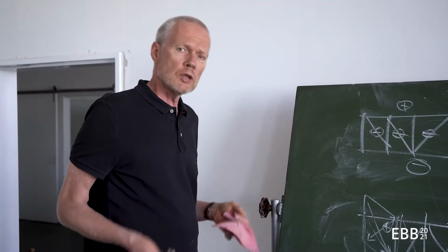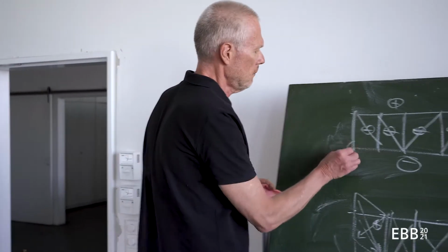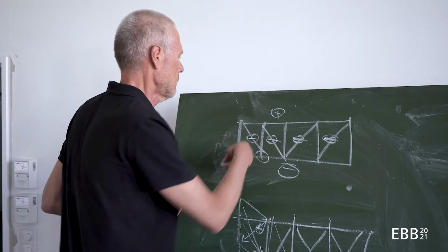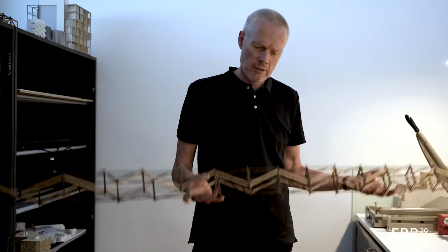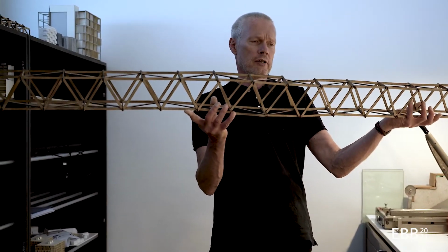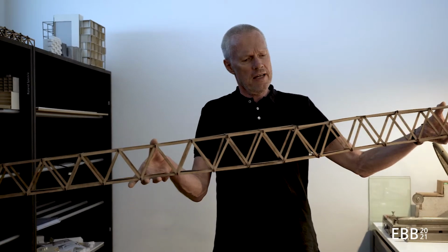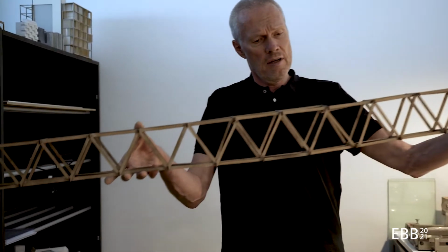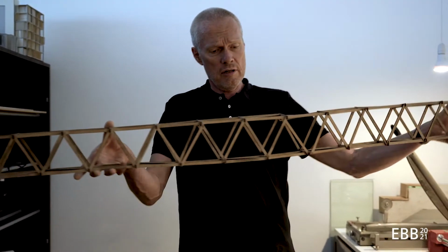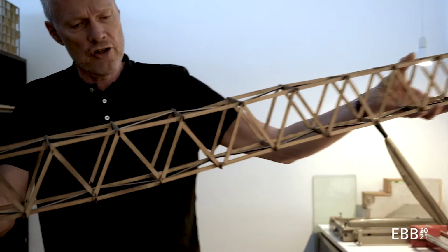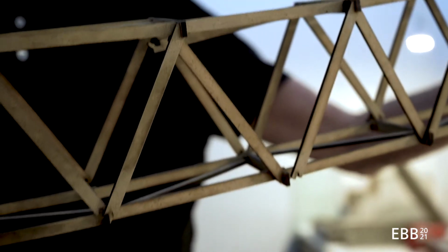Although you can see in older wood trusses that the linkage here was not that easy at the time, so sometimes in wooden trusses the diagonals are the other way around. So unfortunately this wonderful bridge structure that my students did here is broken, and you can see though in how far the diagonals work together with the upper and the lower chord, and where I take the diagonals out because the connection is harmed here, the geometry of the truss starts to move and it becomes fragile.